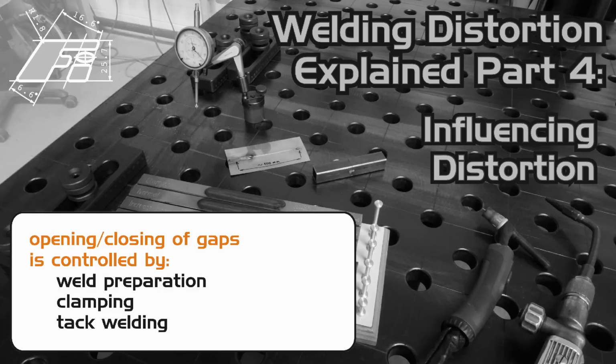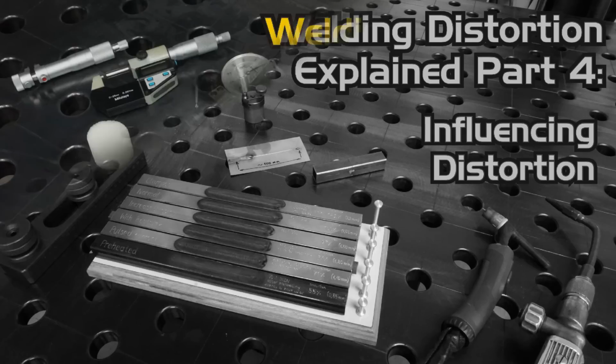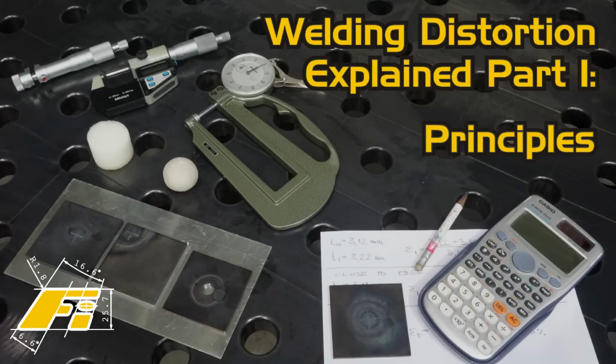This is a quite straightforward geometrical problem and therefore only discussed in the last episode. This video series should assist in gaining an understanding of the primary mechanism of welding distortion. Of course, this will not allow us to forecast distortion quantitatively, but rather qualitatively. This understanding should also enable one to plan tack and welding sequences that result in lower distortion than using no particular sequence. Also, it is crucial for flame straightening, where key to success is to smartly decide about location and size of the heated spots.